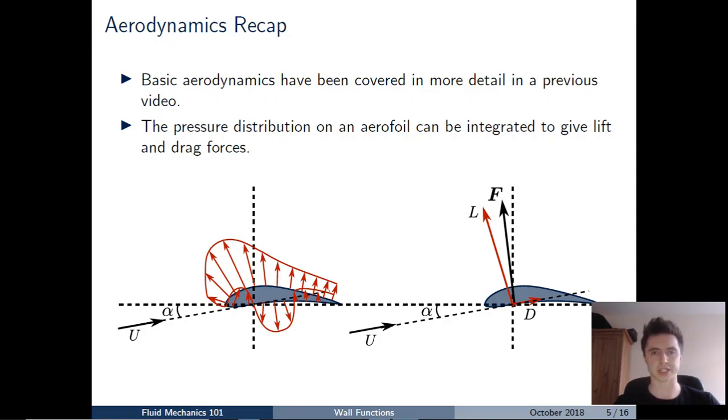So before we proceed, the main thing we want to flag up is the effect of this angle of attack alpha. So what happens is, generally as the angle of attack increases from 0, what we find is that actually we get an increase in lift and an increase in drag. And what that might imply is that if we want to get a greater force on our lifting section, then we would just continue to increase that angle of attack as much as possible.